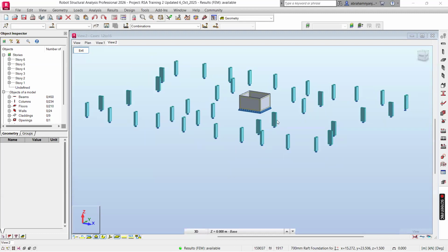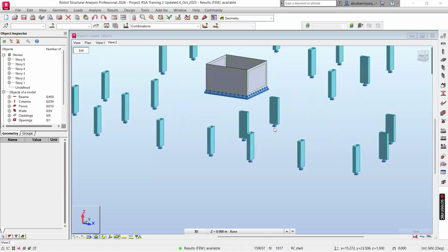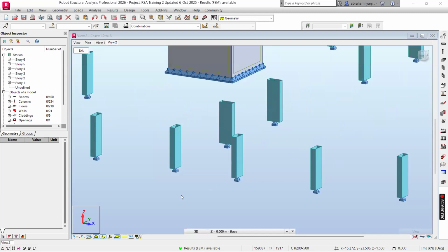As we are going to see here, we are going to design for this column, for this footing, but we shall go on designing others. For example, the edge columns are critical. There are those that we shall design, and probably footings cross one another, so we shall adjust them. But for the start, we shall start with this point that has the greatest FZ. Now this is a column, but our emphasis is on the node because we are tackling footings.